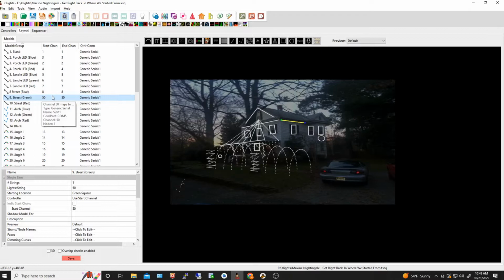Because I have these solid state relays that I'm just controlling. With solid state relays, you can have different levels of brightness versus mechanical relays. And that's all controlled through your PWM, but you only get like a dozen PWMs. So you have 52 channels, but you get like a dozen PWM channels on a Mega.